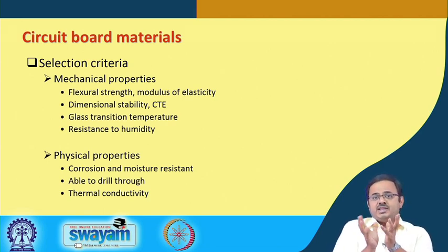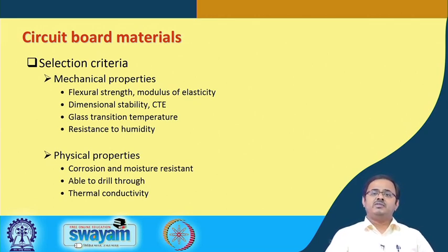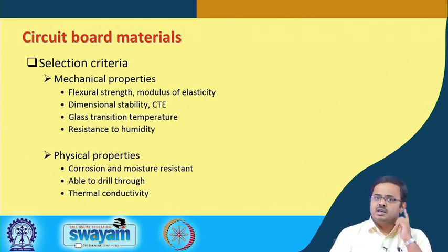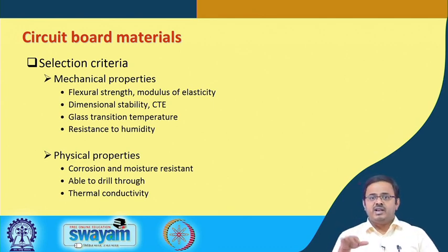Also, in areas where there is very dense circuitry, the thermal conductivity will be more because you have more copper, more traces over there. Okay. So, knowledge of this thermal conductivity is very important, especially when we do thermal modeling, and particularly for those packages which are not flip chip package, where you do not have a dedicated thermal solution on the back side of the silicon and you depend primarily on the conduction through the motherboard.